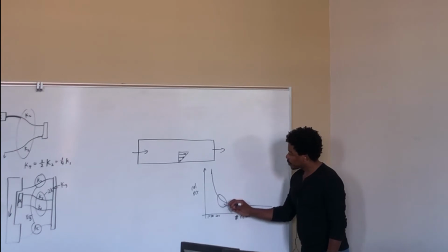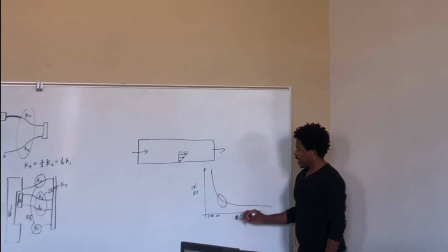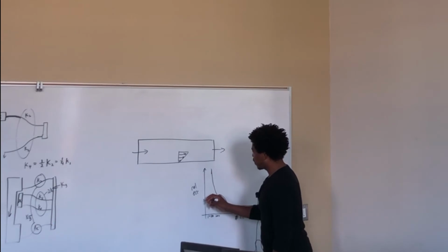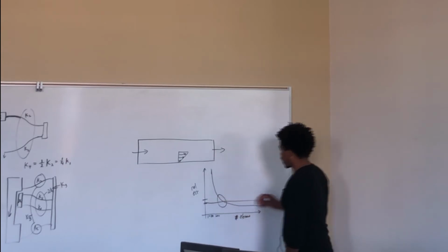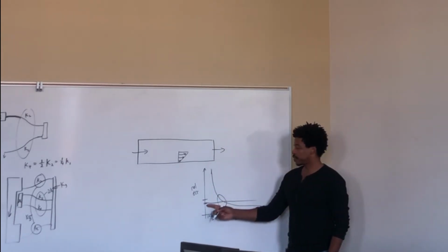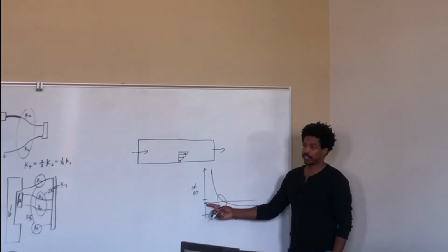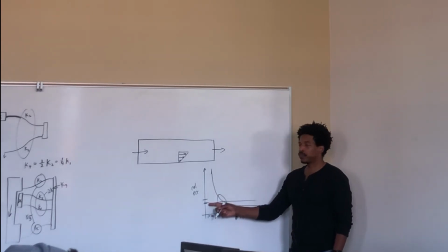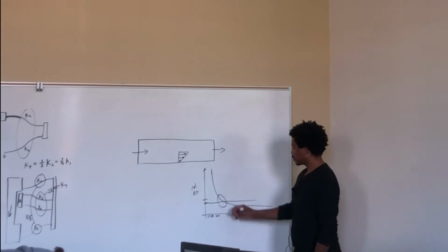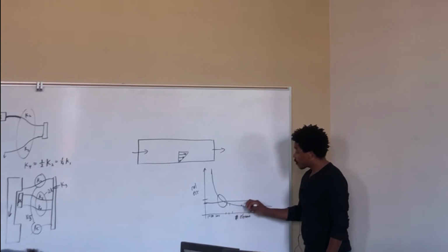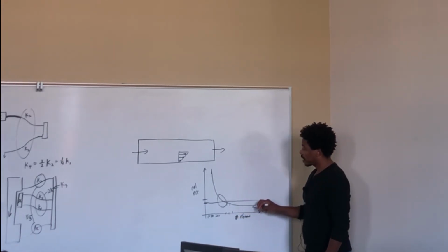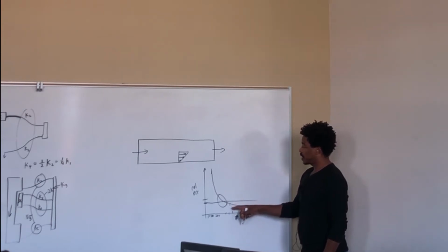But then after a while, you pass this convergence knee, and let's say all you care about is an error at that level, or this level. So anything below that is fine. Let's say this level is maybe the second, third, or fourth digit. So you don't care if the 7th digit or the 9th digit is accurate. You just want the first 2 or 3 digits. So that'll get you that. So any more meshing you do after that, you'll get more and more accurate or more refined, but it's not getting you